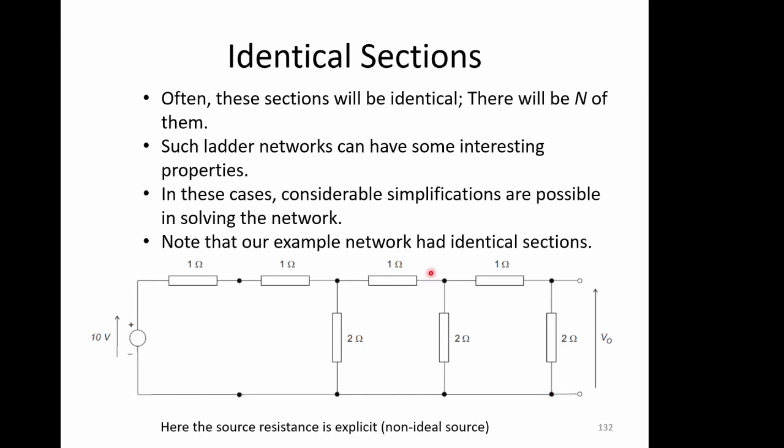You could say it's also a star connected to a delta. You can see that you've got a backwards L here if you absorb that back into the source again. So there's lots of ways of viewing this as a section. So what we've done here is split this source, and we're going to be looking at it in these backward L's, upside down L's.